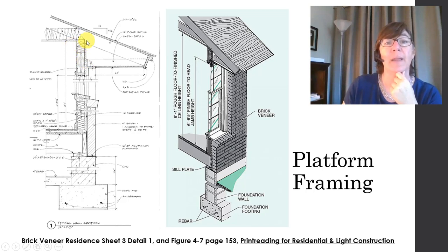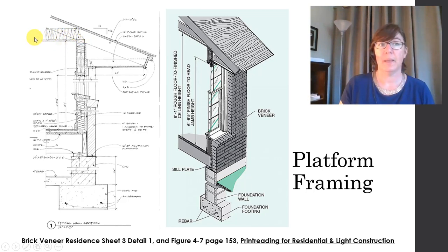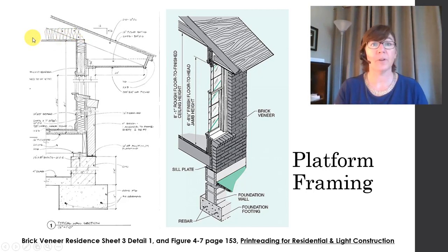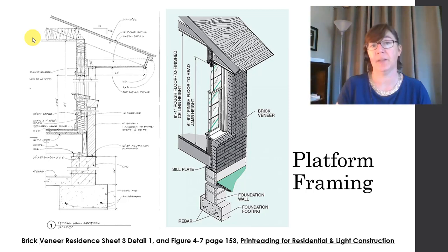At the top of the wall right here is our double top plate. And that is right here in our three-dimensional view. All right. The ceiling joists are going to come across right here. And remember this little S symbol in the construction drawing is showing the insulation that is laid in between each ceiling joist.